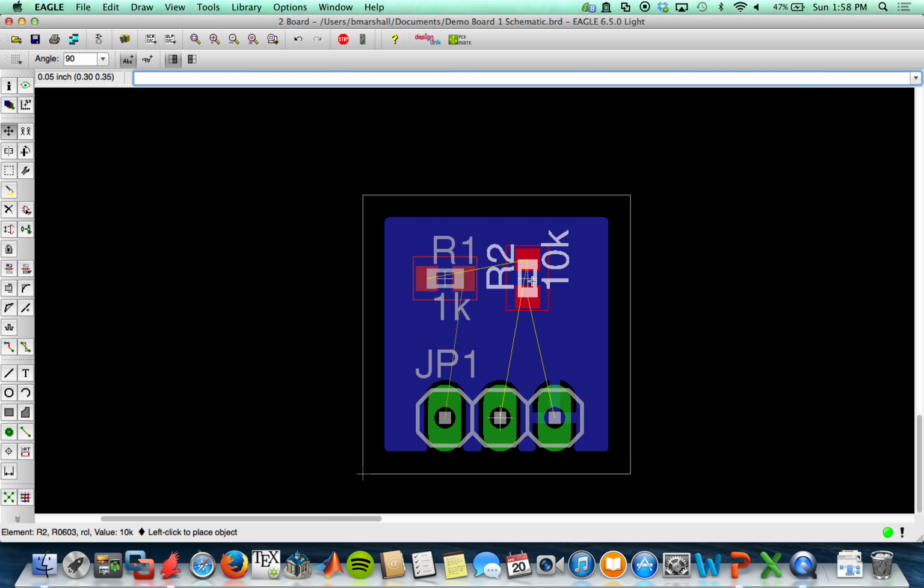So I'm going to right mouse click to rotate after I select it on move. And I'm going to know it should be right next to this V out, like that. And this guy, the air wires look best something like this. So maybe I'll shift this guy up a bit. Okay. And again, this is not a great layout, but I'm doing this just to show you what it's like. So notice this is ground, and so it tells me to connect between these two, but that's probably not the best way to go because I know the ground is directly underneath here.